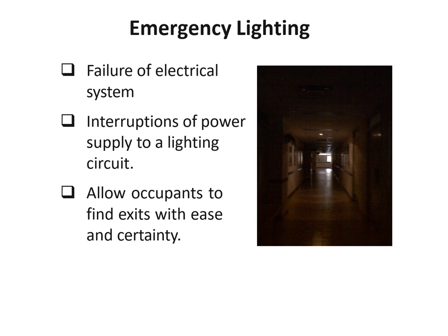It allows the occupants to find the exits with ease and certainty. So in the photograph that you see, even though all the power shuts down and the entire electrical supply to the building trips, the emergency light will come on because it's routed to an emergency power supply. And with that, it's just sufficient light for the user of the space to know where to go. So just functional, in the simplest of ways, to point towards the exits.